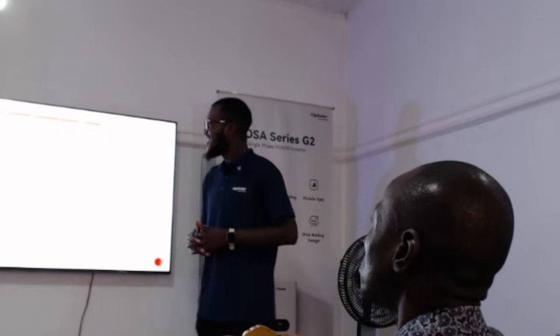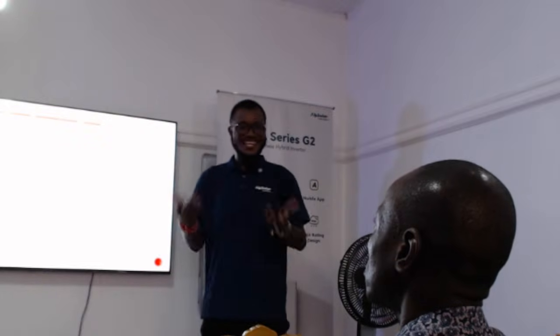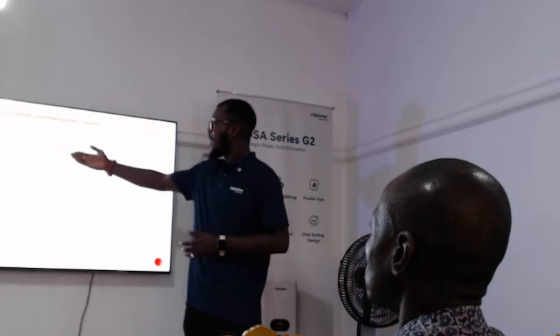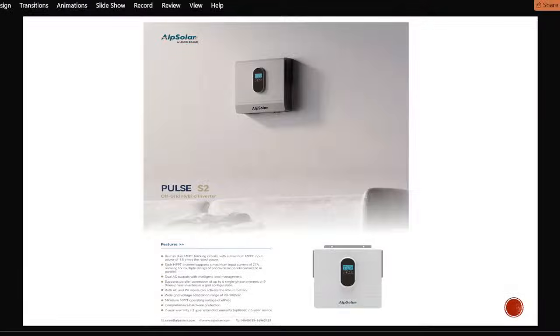Also the maximum input voltage is 500 volts and the voltage range is from 60 to 450. This is also a key feature, whereby it starts to charge as early as possible, and even late in the evening, around 6:30, 7 p.m., you are still getting something to charge. Also 2 MPPT, 2 strings from the connector. That gives you the capability to go for a wide range of PV.